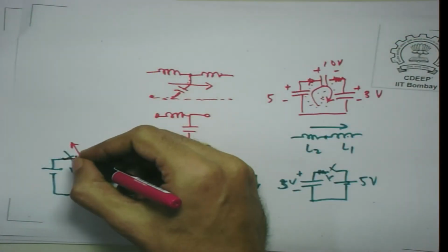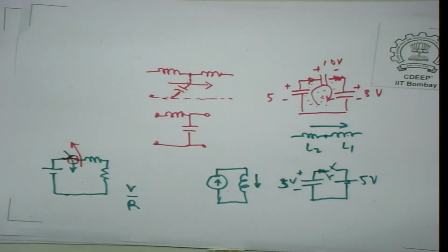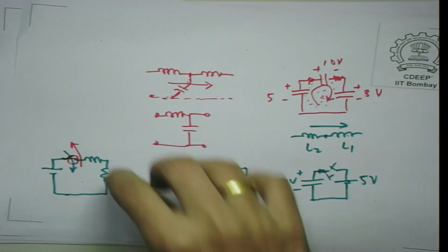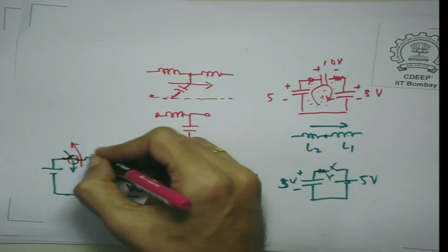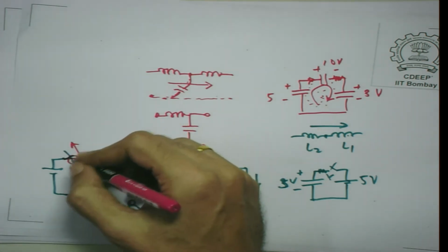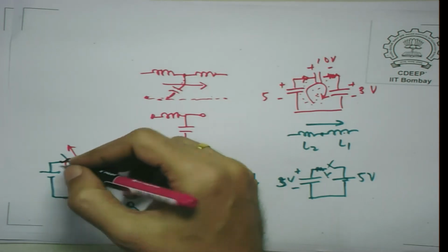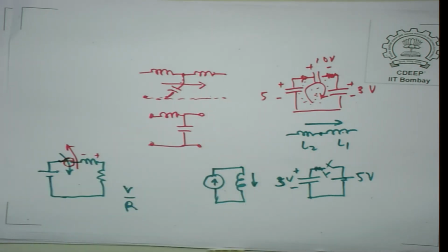So, the voltage across the inductor would be infinity, but again the non-idealities save us, because when you actually try to interrupt this current, the voltage starts rising, and when you open the switch an arc is formed. So, the current really does not interrupt instantaneously. The high voltage which appears because the current starts dropping as you open the switch creates an extremely high voltage across the switch, which breaks down the insulating medium between the switch contacts, and that has an arc. So, the current actually does not extinguish instantaneously.